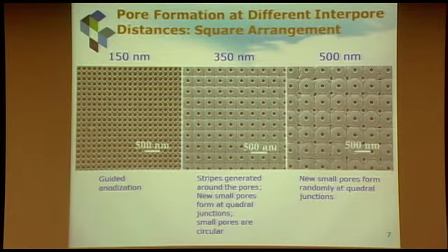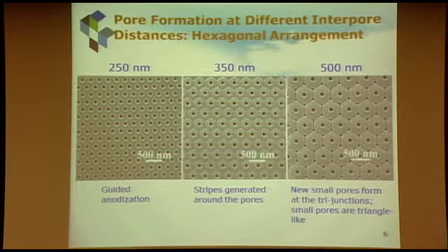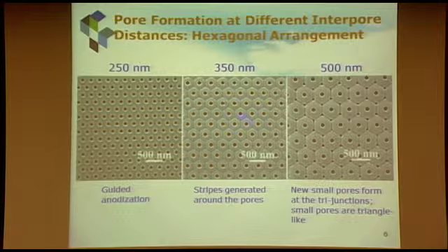And those are all fully anodized? When you say fully anodized, what we're seeing on the surface is all aluminum oxide. Yes, they're all anodized. What you see here, they are all oxides, but you cannot tell the boundary, so it's one color. But then here you start seeing this hexagonal outer layer is the oxide layer that belongs to this pore, and then this one belongs to this. You see the boundary for these oxide layers. That's why you start seeing a cell structure on the surface.